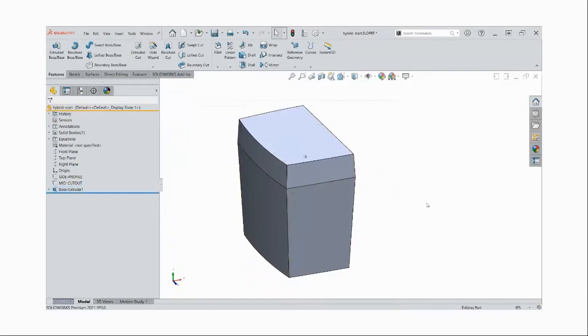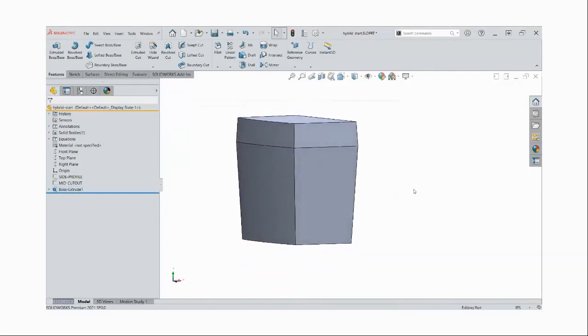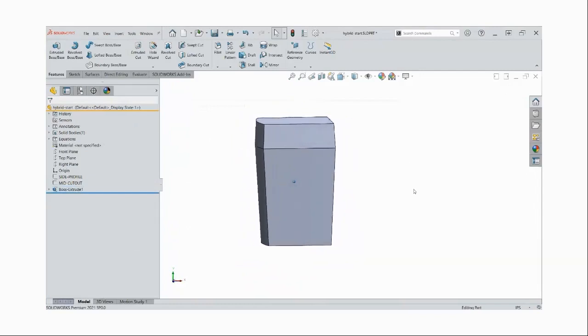So it's just a real crude drafted shape right now. And one of the problems with this method is it drafts all the faces. When you use that draft button in the extrude, it drafts all the faces. So we also drafted these faces right here. And I'm gonna eventually want to mirror across that right plane. So that creates a problem for me.